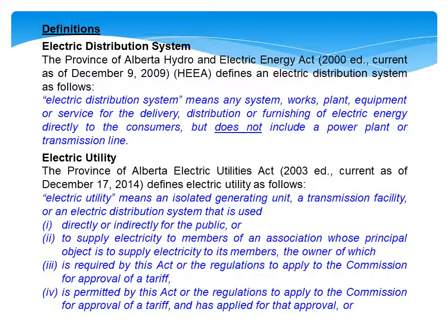Grounding and bonding requirements for generating stations, substations, overhead and underground utilities, as well as for buildings, pipelines, fences, and other objects in proximity to generating stations or substations, are explained in Section 6 of the code. And Section 8 of the code includes rules related to installation of substations and electrical equipment. This section covers rules related to working space near electrical equipment, safety provisions related to liquid-filled electrical equipment, guarding and protection of live parts, including substation switch yards, and circuit breakers, switches, and fuses.